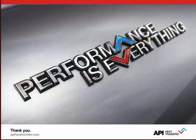All right, thank you. A lot of questions like these coming in. Is there an equivalent to TEMA for plate and frame? No, not in that regard. There is the API 662 that defines the general rules. And on the other side, the variety of plate and frame heat exchangers is much smaller than on the shell and tube side. For example, the TEMA type describes the head and the rear for shell and tube, but for plate heat exchangers this is always the same. So there is no variety in this regard.